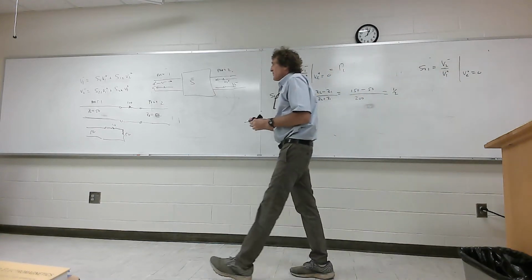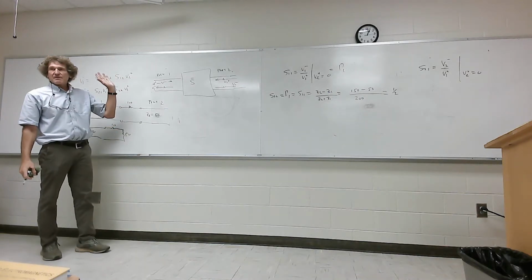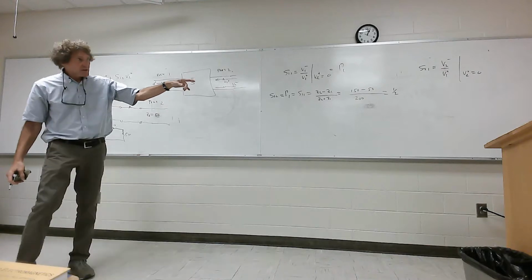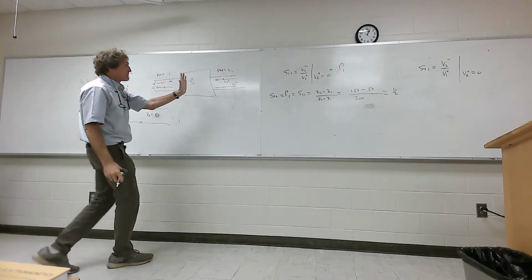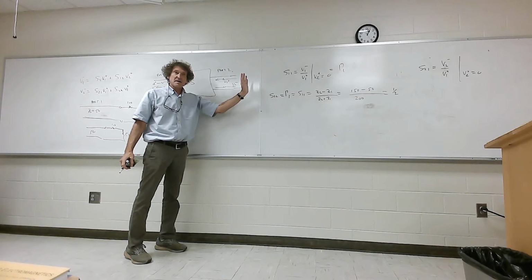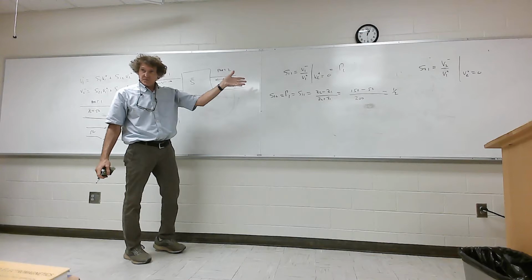So this is the forward voltage gain. If I take V1 plus and multiply it by S21, I find out what this voltage is, the waveform coming out of that port. Y'all follow me on that, class? That's an important characteristic. It's really called the forward voltage gain.